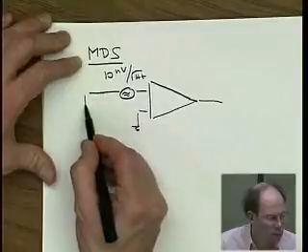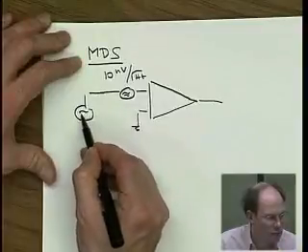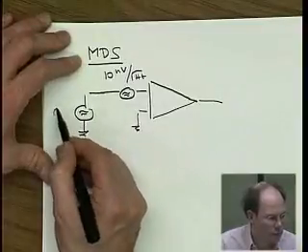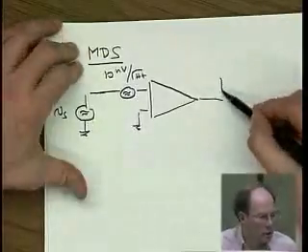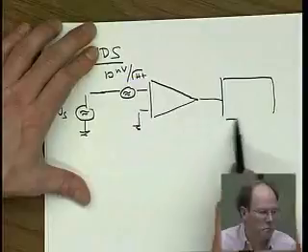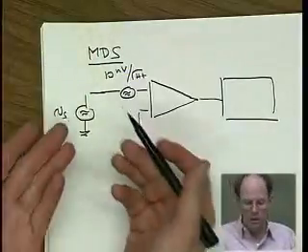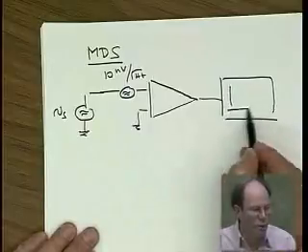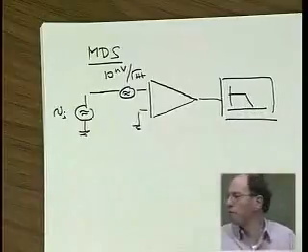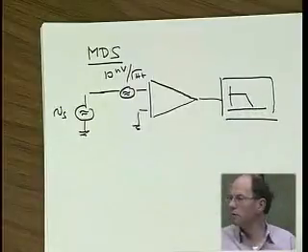And you also hook this up to a sensor that puts out a voltage Vs. For example, this is a microphone, right? You know that ultimately this is followed by a low-pass filter. It's going to look at only the first 10 or 20 kilohertz of the signal.